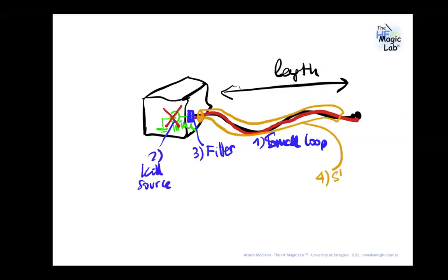Sometimes people add shielding in cables, and in the end it is the screen of the shielded cable that is radiating. So it's very, very important to make a very good connection of the shield to the chassis. So I think that these four solutions are the most important things you can do.